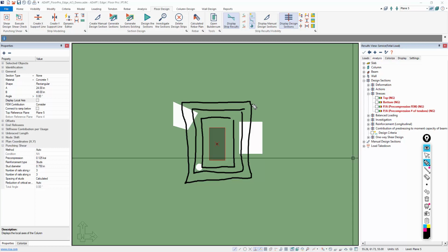So at that location, we convert this critical section to the least critical section, which in this case would be an octagonal shape, assuming our rails are laid out orthogonally along the column like so. So the least critical section for layer 3, we check that as a rectilinear section, and if we find there's no reinforcement, we immediately convert that to this shape. We then check the stress on that critical section.